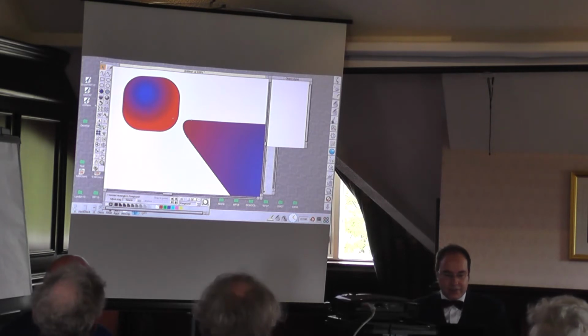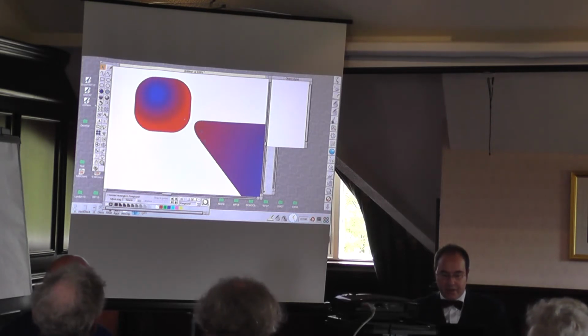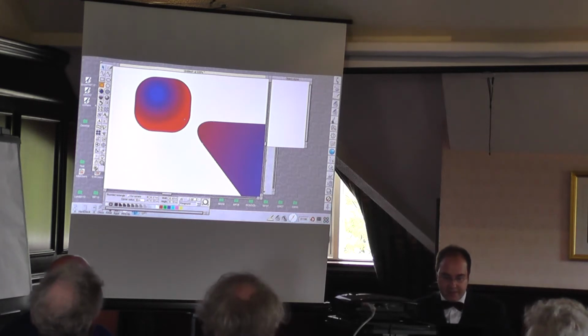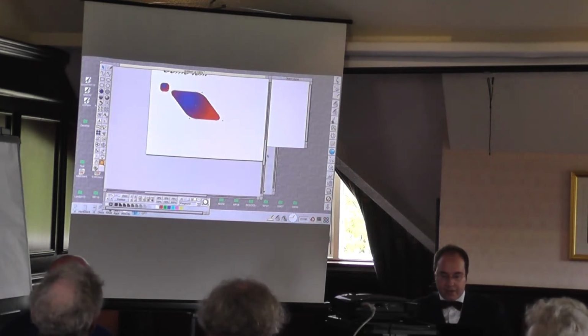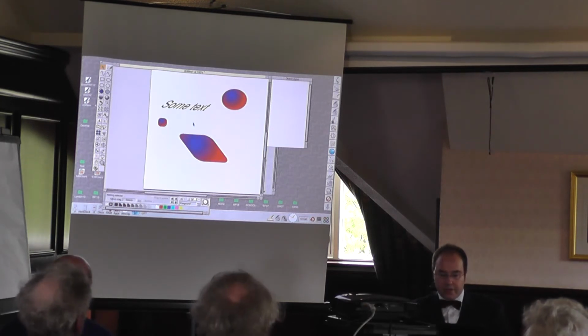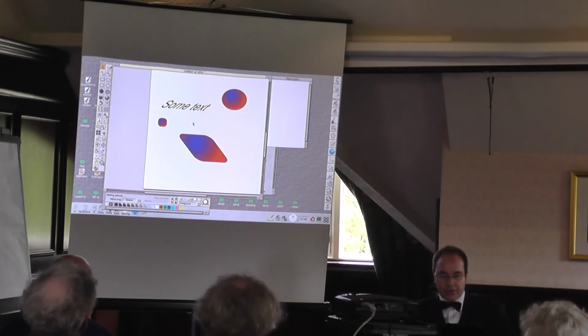In this skewed case, it's no longer anything like that, but still you can go to the rectangle tool and make the rounded corner larger, say from 5 millimeters to 8 millimeters. And that still works even though there is now an additional transformation applied. And that's the general idea of all the mathematical transformation operations in Artworks. You can apply most transformations to most objects.